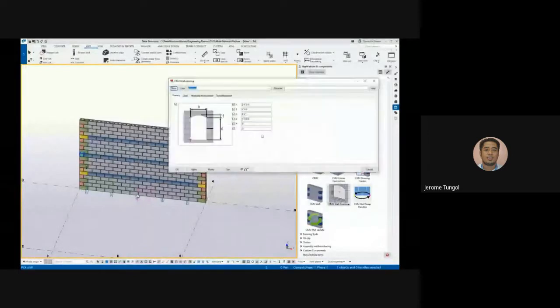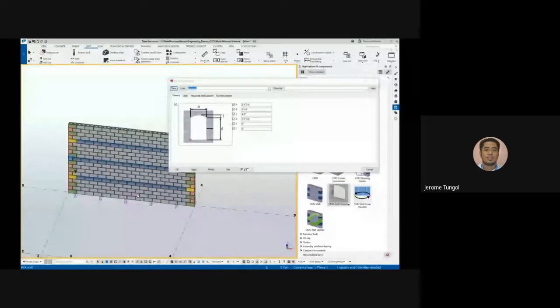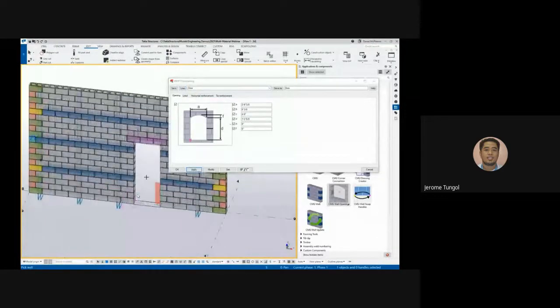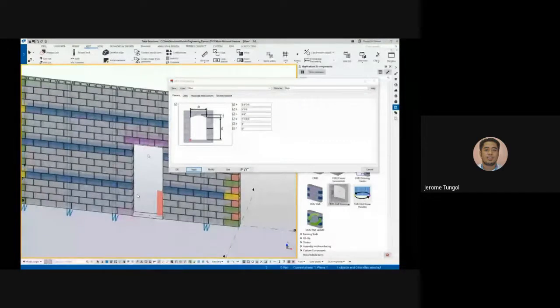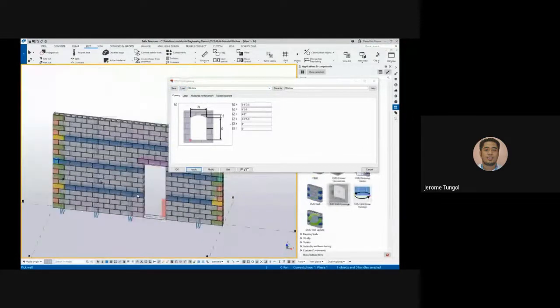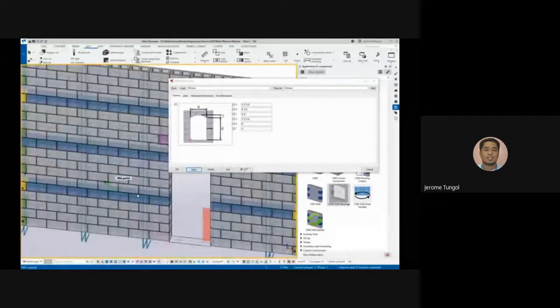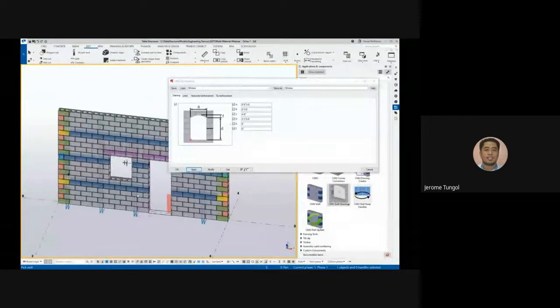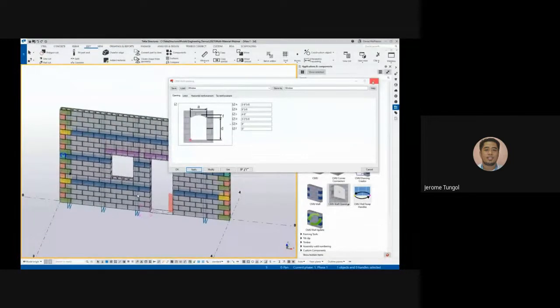And then the CMU wall opening, you also see it in the component catalog. From the catalog, input the right size of the opening and then click the position where you input the door opening. Then just adjust, load this window, and apply again. It's better to model if you have a reference model, just like the wall earlier.